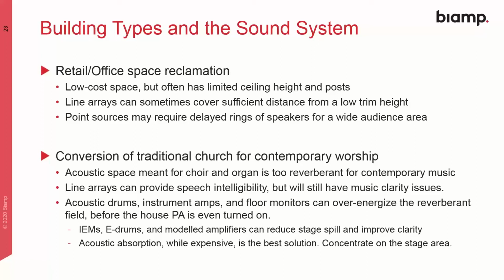Acoustic absorption, while expensive, is still the best solution. Concentrate on the stage area and also the rear of the room, particularly if you've got a line array directing sound toward the rear. Make sure when it gets to the back of the church, it stops and doesn't bounce around from there.